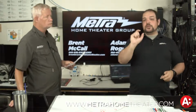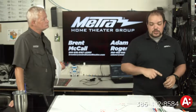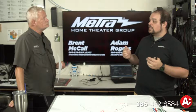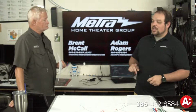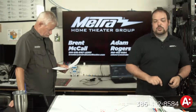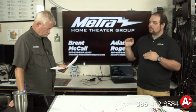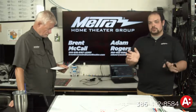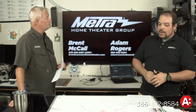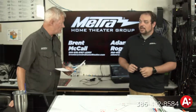So the way it works if you have a PoE device is that the system will turn on, it will look for that specific amount of resistance, and if it gets that resistance, it will then do the next thing. It'll find out what type of resistance. It sends a couple other pulses of voltage down the line. It will start at 2.7 volts, and then increase from there until it gets a specified amount. I'm not sure exactly what that is. You might have to do a little bit of research on your own. 10.1 volts. The max of 10.1 volts. Right. So we don't know. It does not give us a crossover chart from impedance to voltage.